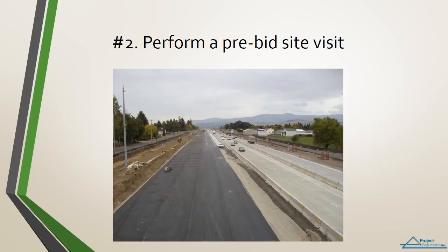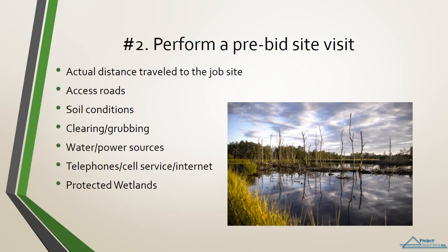Number 2, perform a pre-bid site visit. This may seem obvious, but this step is often overlooked by contractors who are either inexperienced or overly confident that they know the details of a particular project. Visiting the proposed job site is critical to a successful estimate, as it may bring to light concerns that are not readily apparent in the contract documents. The following is a list of some of the items that contractors should check for when making a pre-bid site visit.